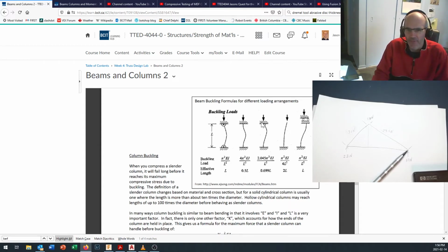Over here, you can see, well, if it's pinned at one end and flexible at the other, it's going to be about twice as strong. But if you're only braced at one end, this would be like taking a pole and planting it into the ground. So a big piling or something, you're making a fence post, maybe a tree, the amount of force that it could hold up at this end would actually be 1/4 what it would be as if it was pinned at both ends right here, because here it's free to flex back and forth from side to side as well as bend. And condition here where it's planted at the end but has a roller on the top.